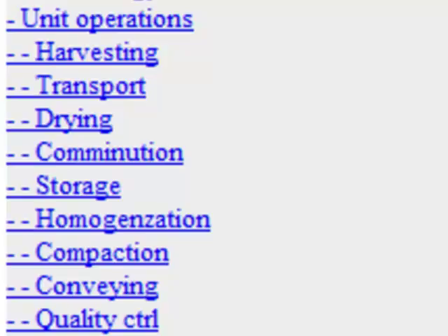But it is also very closely connected to the uniformity of the material, i.e. to its heating value. Because most conveyors, be it a screw or a conveyor belt or a cell feeder, will dose volume. They will not dose mass.